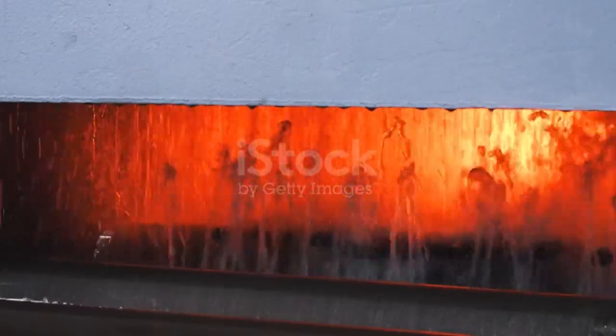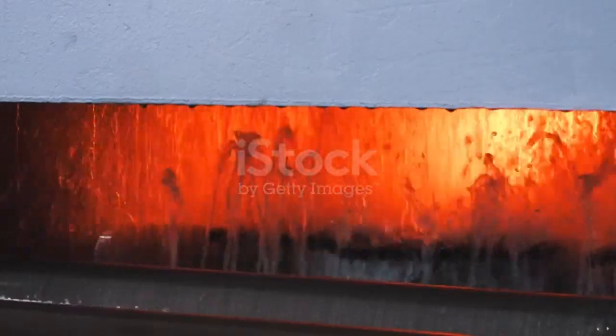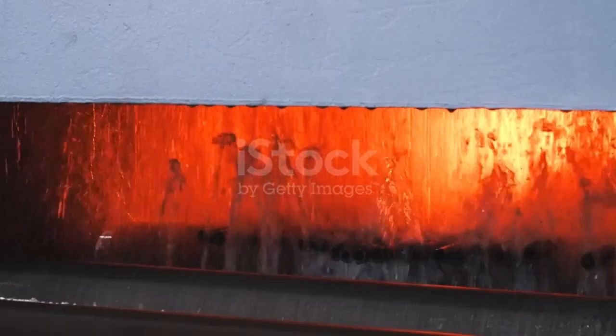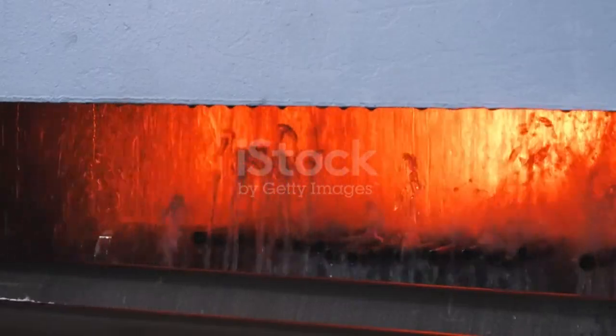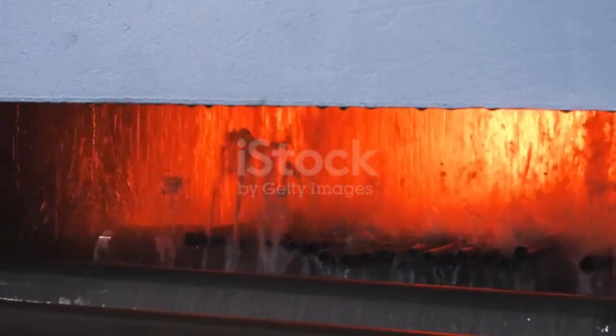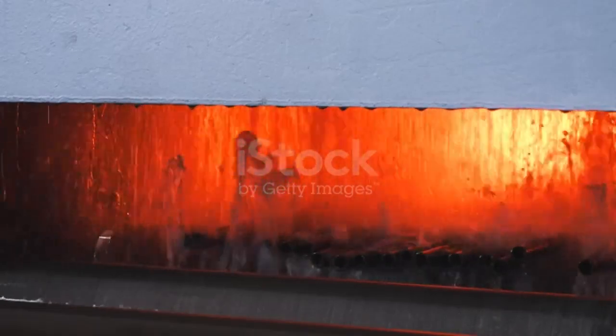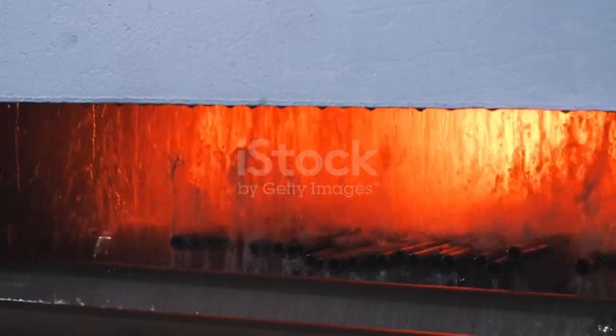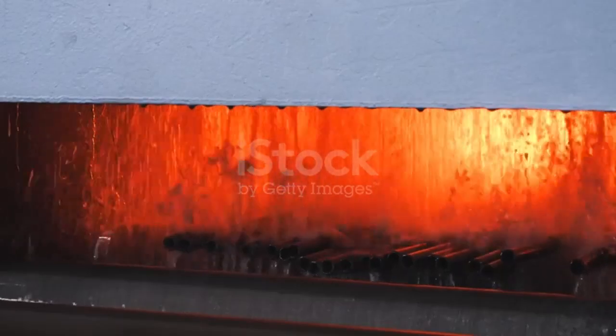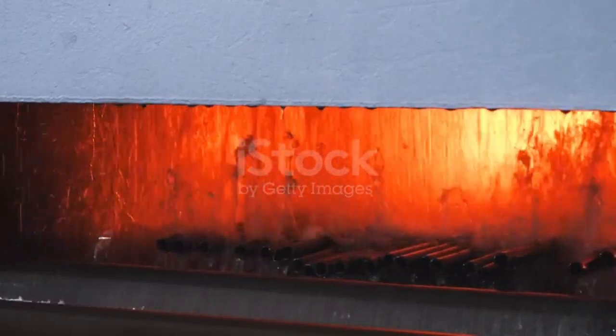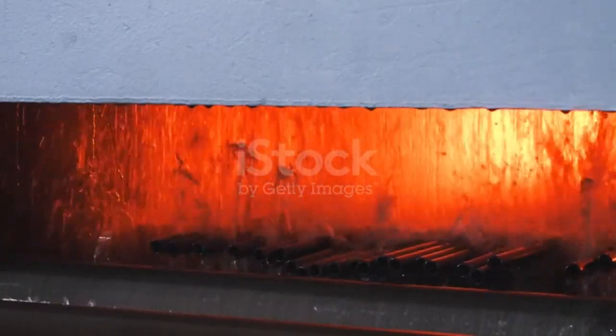Scene 6. Clinker cooling and storage. After leaving the kiln, the clinker needs to be cooled quickly to maintain its quality. This is done in a clinker cooler, where air is blown through to bring the temperature down. The cooled clinker is then stored, ready for the final stage of production.